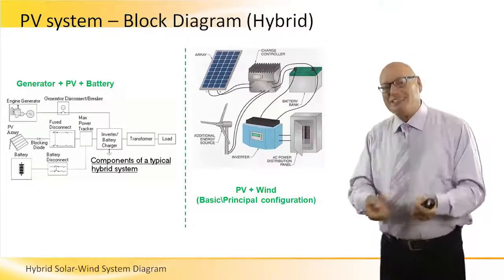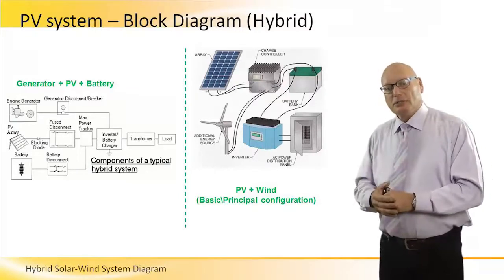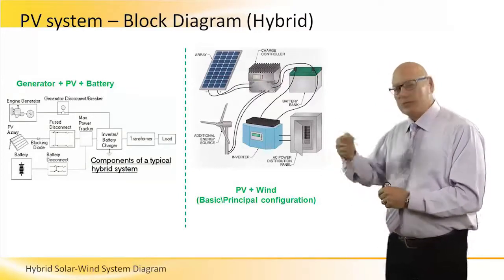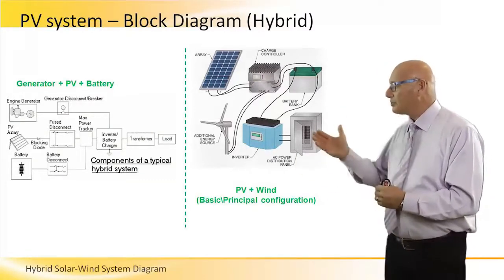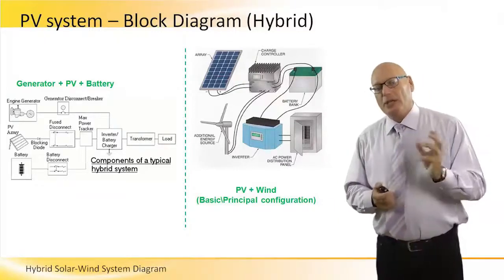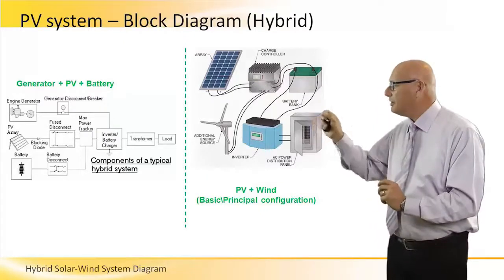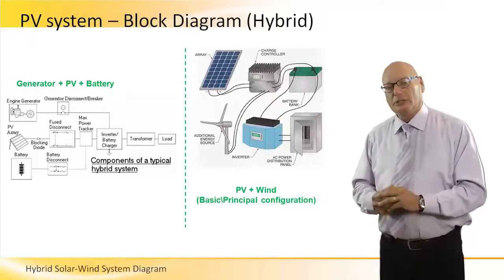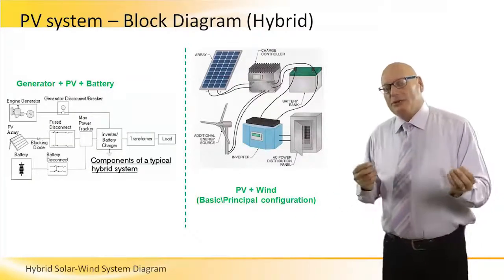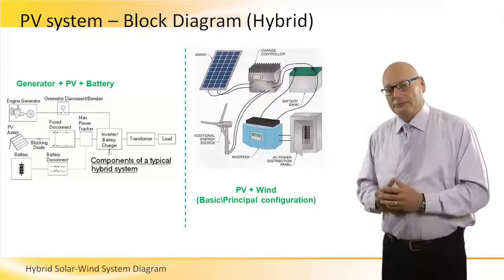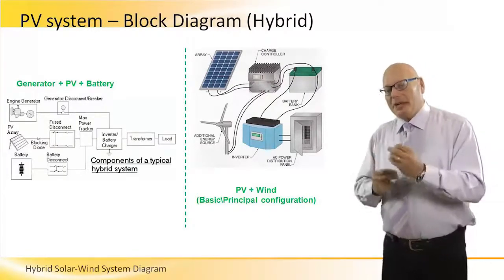The battery, as a third energy source, goes through a disconnection switch and also to the MPPT and goes to the inverter. So these three energy sources, which provide energy to the battery charger and inverter, play different roles at different times of the day. One is being backed up by the other.